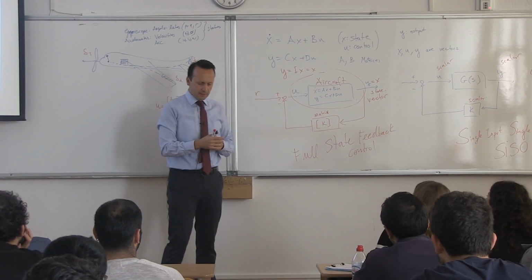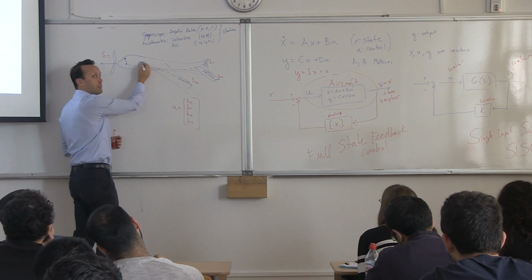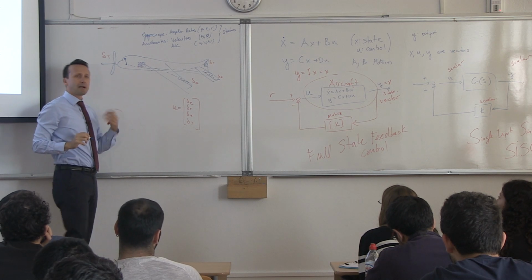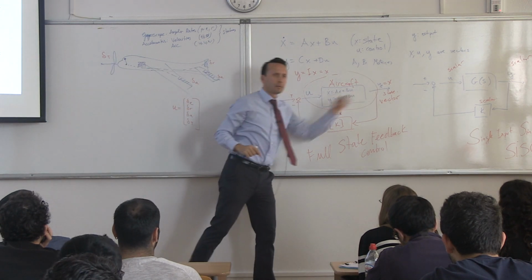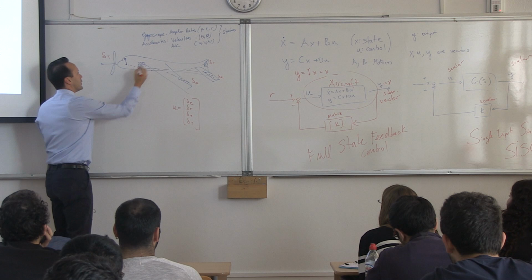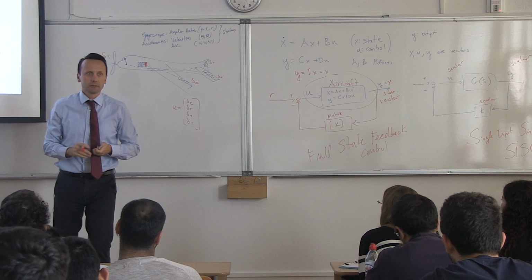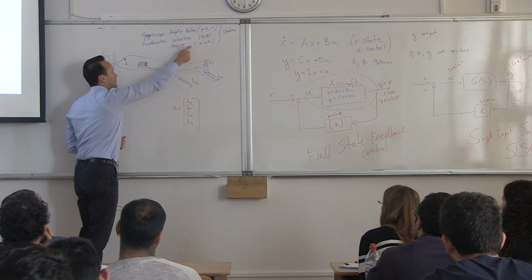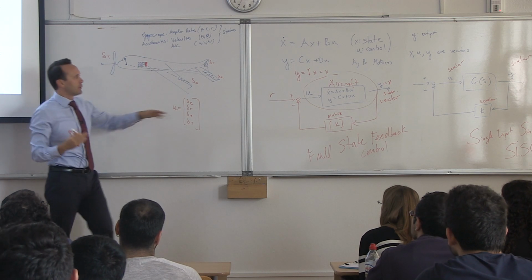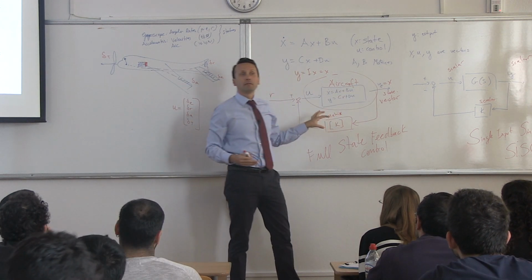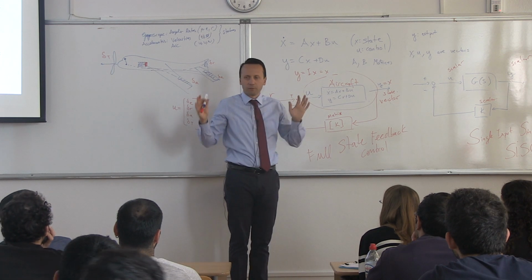So the way we do it is the following. We have all these measurements. Let's say the blue box is the measurement. So we take P, Q, R, theta, phi, psi, and all this. And we add a little computer on it, or a little microcontroller, something that can make a calculation. Multiply this measurement in the blue box with this little red box. We multiply the state with a matrix K. Something that can multiply a matrix and a vector is good for us.